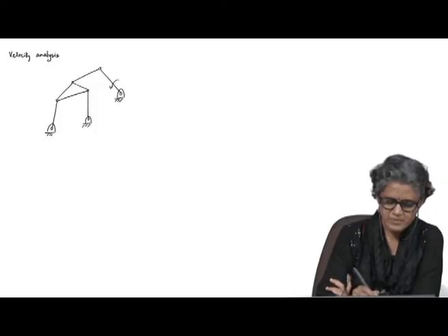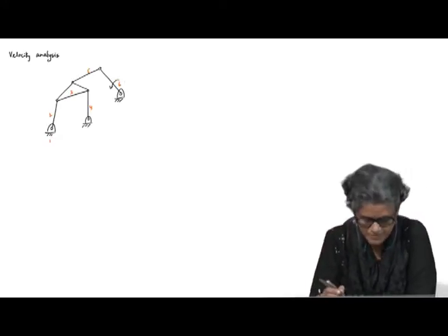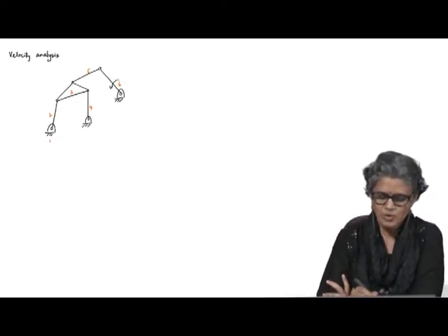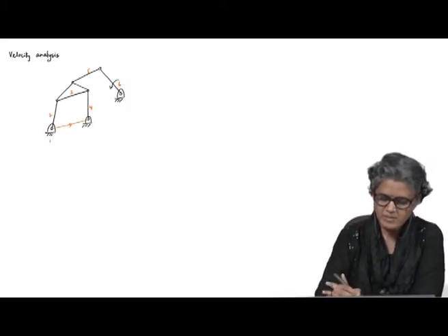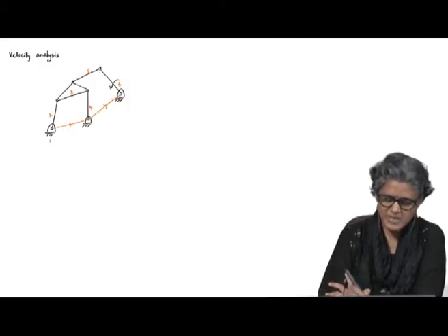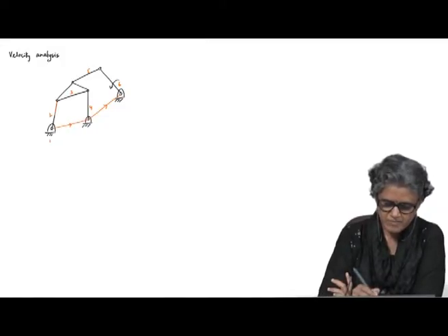Okay. 2, 3, 4, 5, 6. Again, always check for mobility when you encounter a new mechanism. We have seen this a few times now, but this is a mechanism of mobility 1. It is basically a 6 bar Stephenson mechanism. So, I have this.